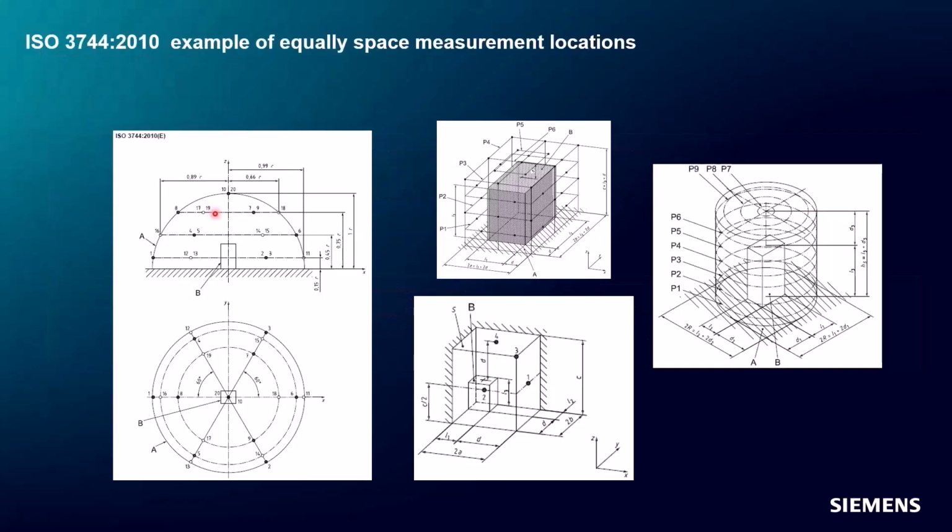This picture shows different arrangements of different microphones. The black dots correspond to the precise location of where the microphones have to be placed for this ISO 3744 standard. And it can be in one corner of the room, or as a hemispherical arrangement, where the source is at the center, or a cylindrical pattern. Different arrangements are possible. So what makes sense in your situation will depend on what type of facility you have. And based on a preliminary set of measurements, you can determine whether that is adequate or not per the standard.